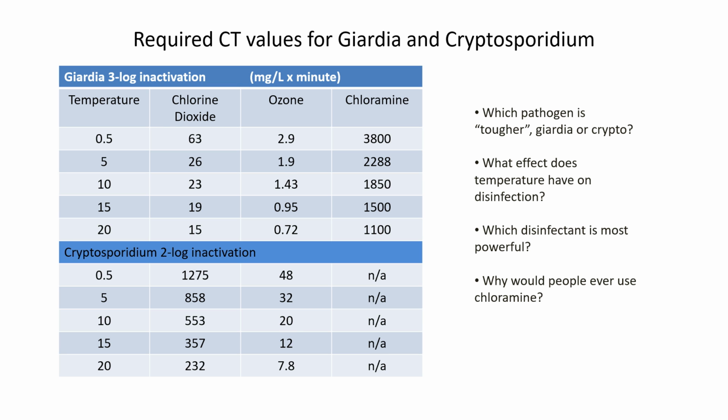And it's considered a difficult pathogen to disinfect against because it forms a spore. It's a very hardy pathogen. Viruses are relatively easy to kill in drinking water because they're so small. The chemical disinfectant can penetrate through them very easily. They don't have a very rugged cell wall. Viruses are just strands of DNA. The same thing with bacteria. They're small, they're weak, they're easy to inactivate.